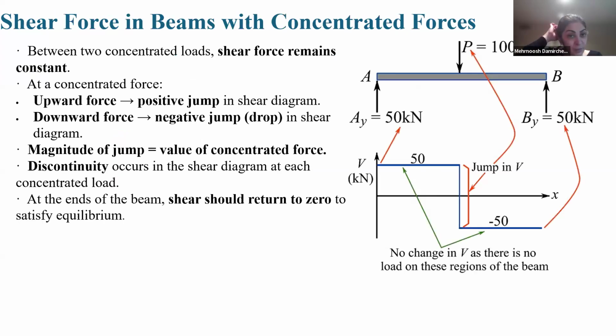Okay. When we have only concentrated force, between two concentrated loads, shear force remains constant. It's easy. For example, here we have supports, and P is the external force, Ay and By are the support reactions.